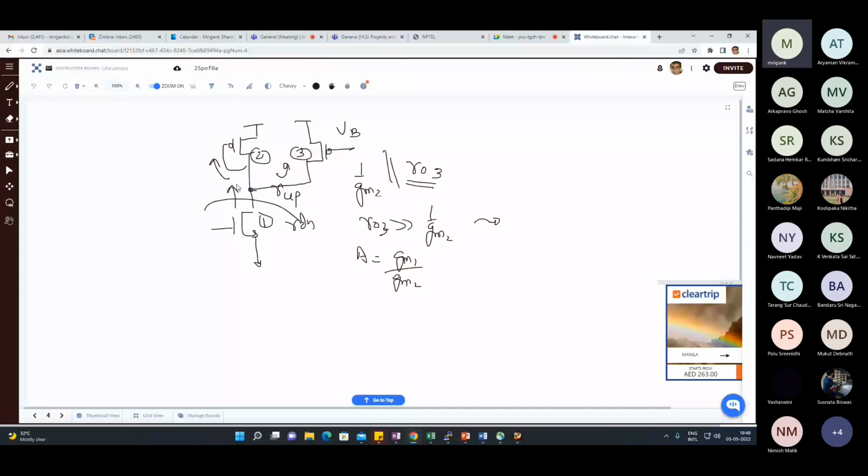So what is the benefit? If you have two loads connected together in parallel, for swing which one will you consider? The one which is limiting. In this case, the limiting one will be this guy because it's still the same VDD minus mod VTP. This is allowing you larger, but if you allow this one to go larger, this one will be gone. This will be in the off region, which you don't want.